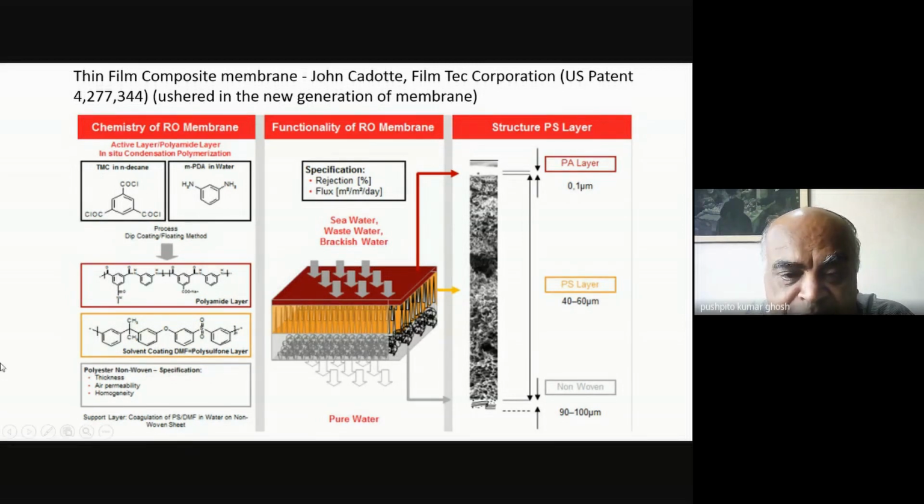What that does is that this polymer, which is soluble in DMF but doesn't have solubility in water, while DMF has solubility in water. So when I take this and pass it through the water, water becomes an anti-solvent, and it leads to the precipitation of this polymer. But the precipitation is not in the form of a powder. It is precipitation in the form of a coherent membrane. And that was the unique part of this particular membrane polymer and the way this processing was done, that you got a continuous film.